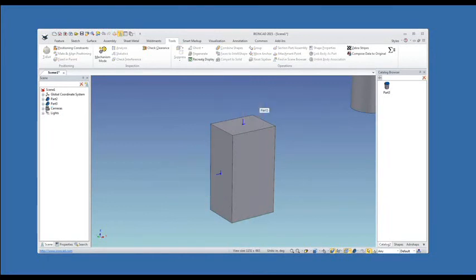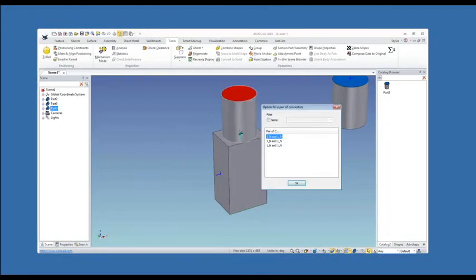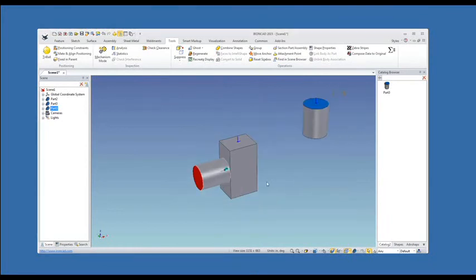However, if you want to have more control over that, like most things in IronCAD, more controls are right click. So I just right click and drag anywhere on the part, and I get this nice little preview, and I can toggle between whichever one I want and say I want that one, and I just hit OK, and then it's done. So that's just a right click and drag out, and that gives you the pop-up to toggle between them.